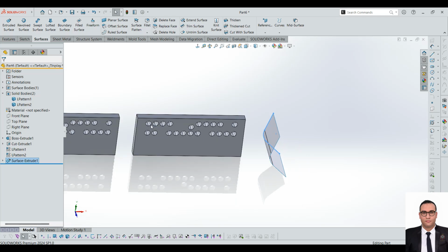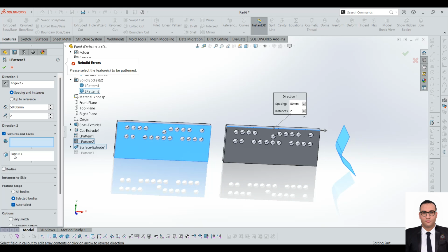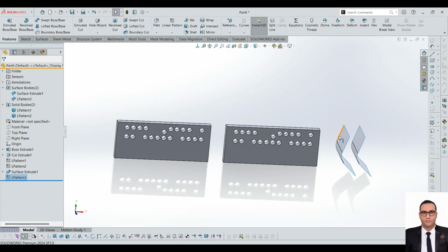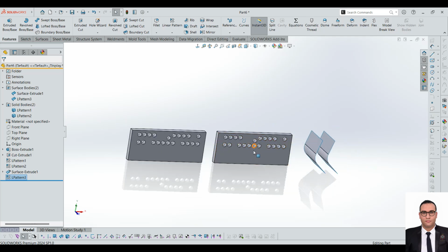See, this is not a body, this is a face, and faces appear here. That's all. If we have a face, we can do it with the function or with the body. Normally people use it with the body, because I consider a face like a body in SolidWorks too. Okay, see here, we select this body and go with this face. Done. See, we have the linear pattern of that face.